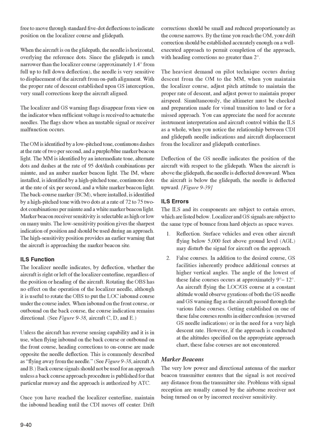When flying inbound on the back course or outbound on the front course, heading corrections to on course are made opposite the needle deflection. This is commonly described as flying away from the needle.